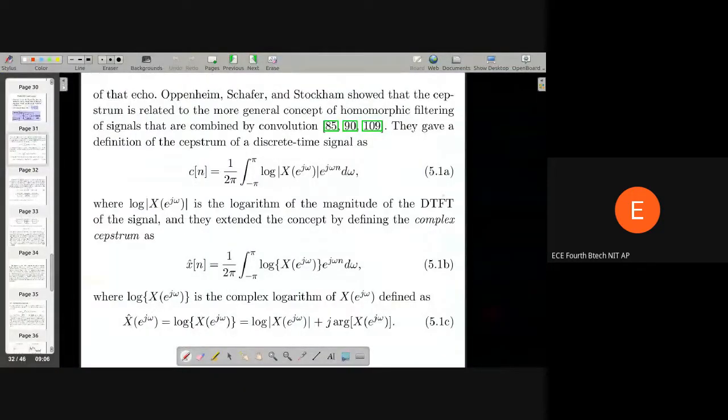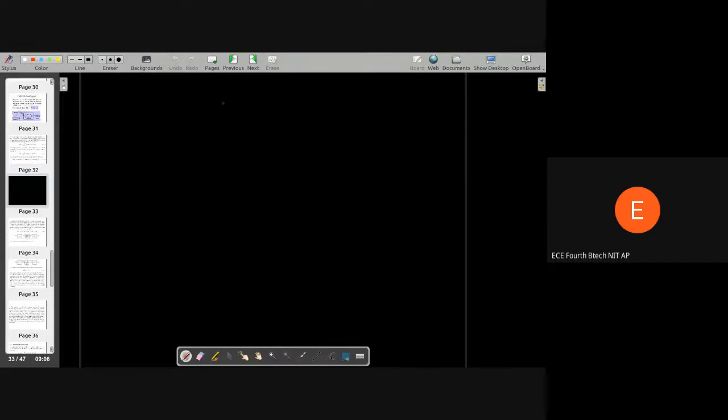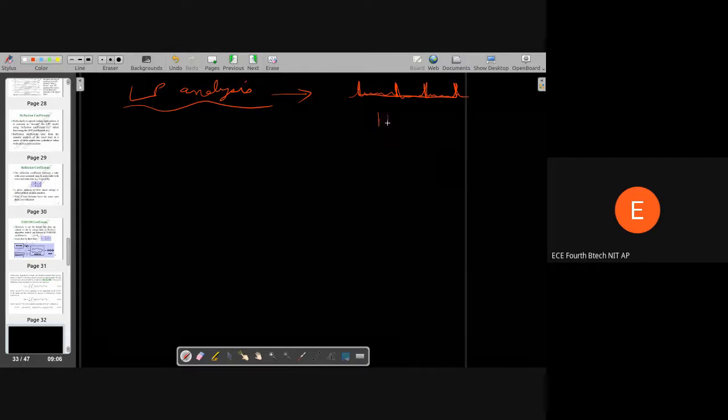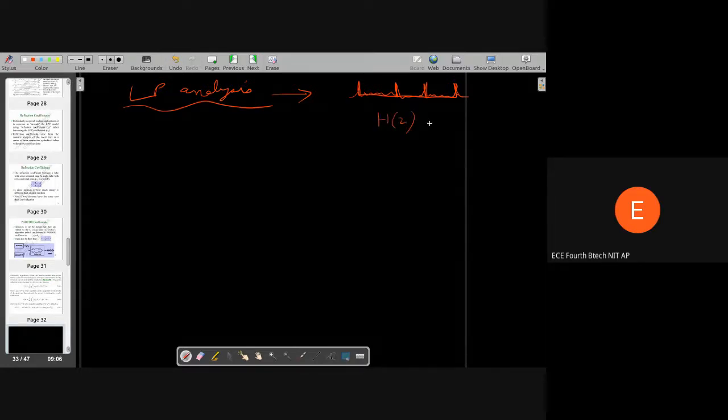So we were talking about LP analysis the last time. And what did we get from LP analysis? We found that LP analysis, or linear prediction analysis, finally gives an error signal which represents, in a noisy pattern, the glottal excitation signal or source excitation signal. And we get the transfer function of the system, from where we can detect formants or vocal tract resonances.